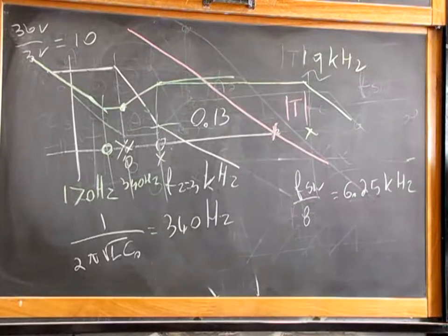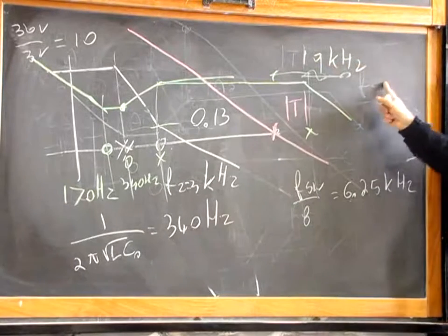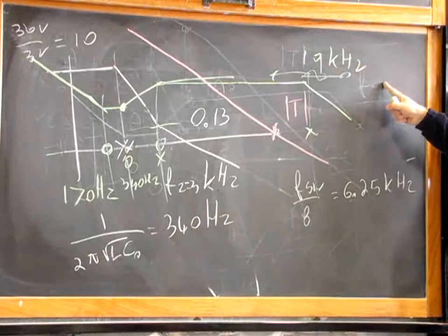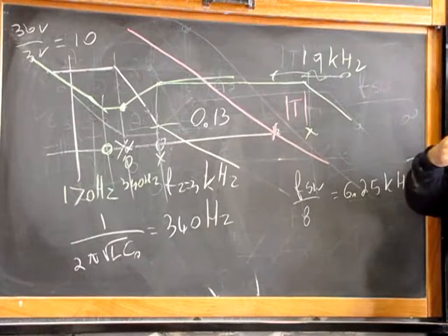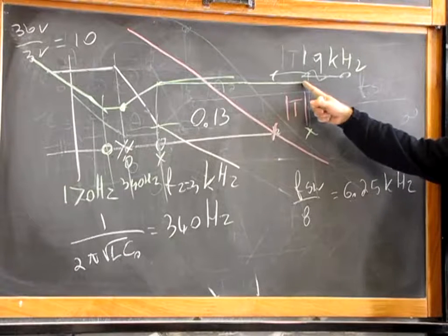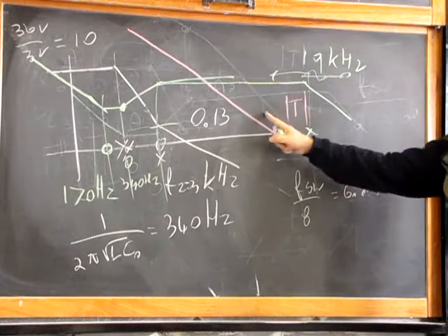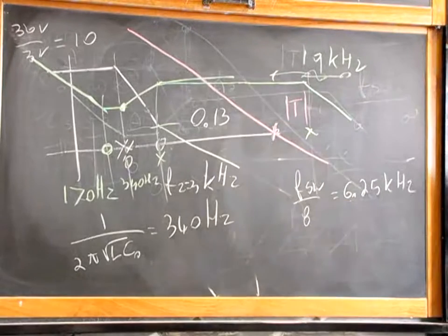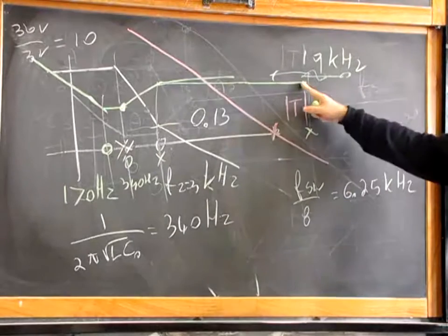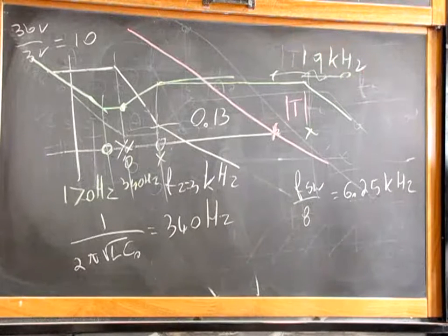I don't like it too much. What are the advantages and disadvantages of moving this closure pole up and down? If you move it up, you have less filtering, less attenuation of the switching noise frequency, but you move your pole away from the crossover frequency, which means your phase margin improves. If you move your closure pole down, you better attenuate the switching frequency, but your pole becomes closer and closer to the crossover frequency, and your phase margin is decreased, because a pole has its effect on the phase starting from far below the pole frequency.